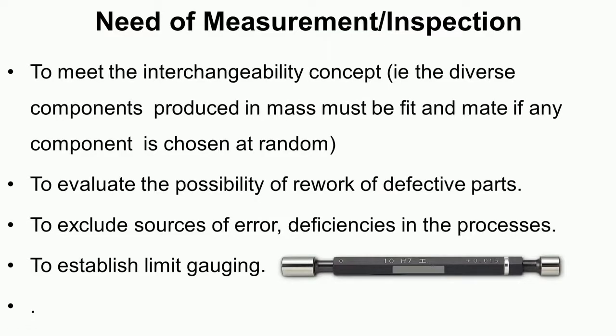Now there is a concept called interchangeability. Due to the mass production concept, mating parts are made at different places and in different countries. When randomly selected and matched, they should fit properly without any individual fitting operation. This is known as interchangeability. To achieve it, it is essential that we produce the various components and parts as per the standard, using standard instrumentation.